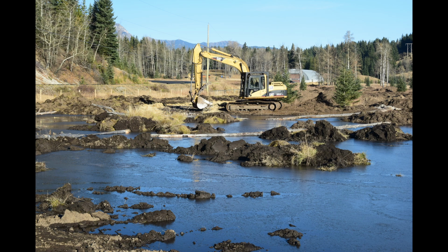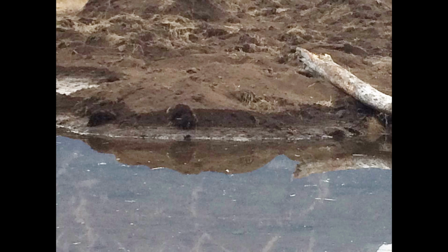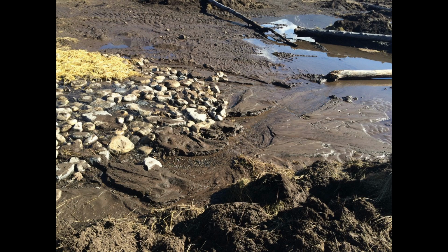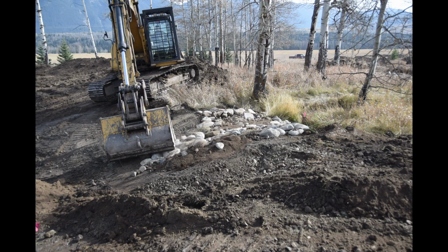They filled overnight. Then we saw a big problem. The stream was cutting gullies around the edge of the wetlands and in the spillways. The silt was dissolving and washing away just like flour. It was not possible to make the water in the spillways spread in a sheet-like pattern so there would be no erosion. There was an urgent need to purchase rock to armor the spillways or the new project would be destroyed. After much discussion about where the money would come from, we decided to order rock so we could armor the spillways. Fortunately, we were able to find a business that would deliver rock to the site.